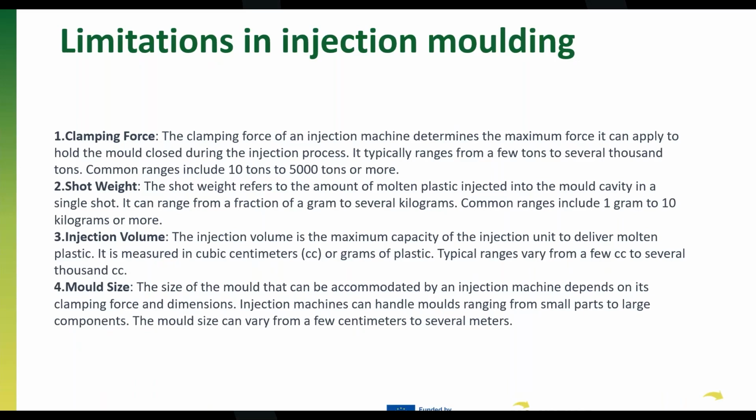Here I have just summarized for you some of the limitations that we can see in injection molding, and I was already mentioning clamping force. This is a point more than limiting because we have a huge range. We need to define what the clamping force of our machine is in order to see if we will be able to produce this part.